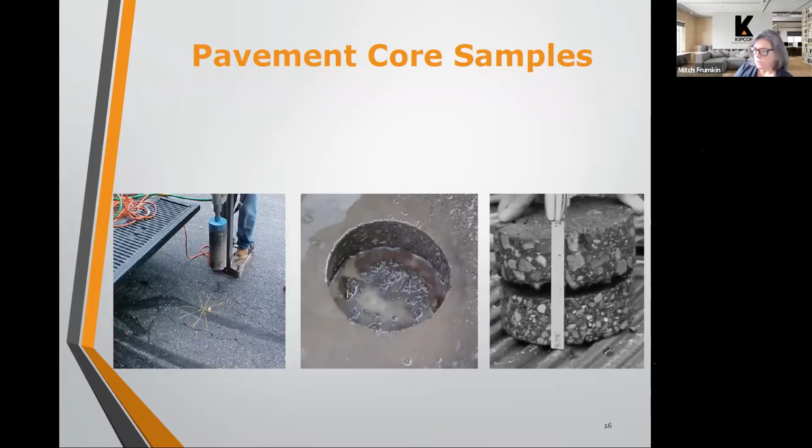So what I like to see when they do pavement cores is the core coming up intact, and if there is a separation, that top layer is at a thickness that when they do mill, it will be completely removed and they'll be biting into that base course.